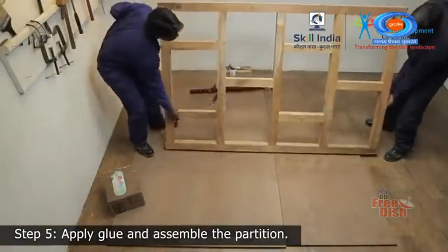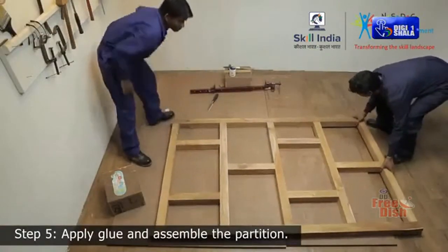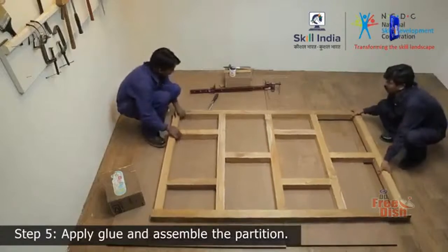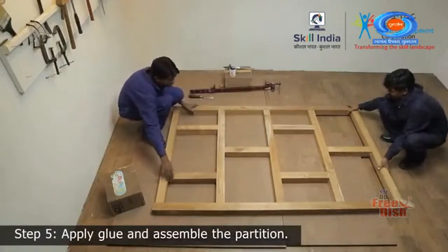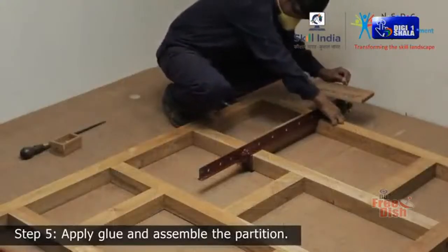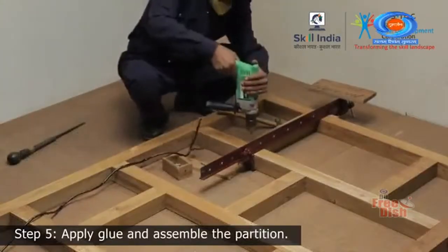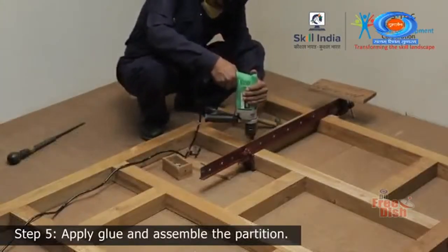Before you move ahead, drive in some screws onto the joints. Place the frame onto the floor and drill holes on all the joints. While doing so, fix the joints with a T-bar clamp, for the joints to fit in and the holes you drill for the screws are at the right place.